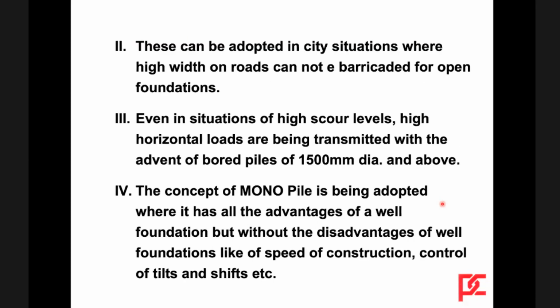These can be adopted in city situations where a high width of road cannot be barricaded for open foundation. In case of open foundation, typically you require a barricading width of about 7 to 8 meters, which is nowadays not possible with the traffic conditions. So that is also one of the reasons why pile foundations are preferred.